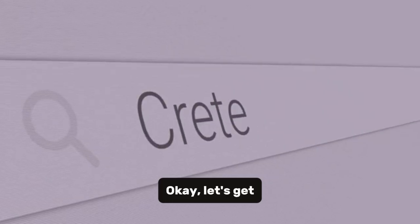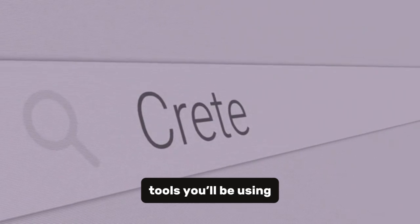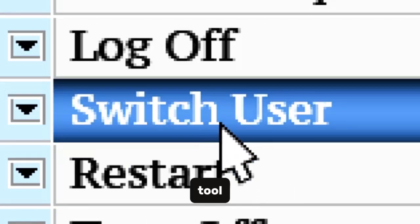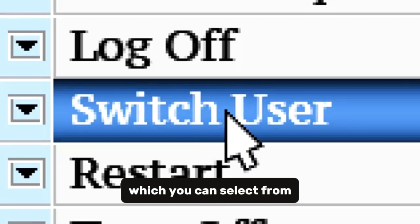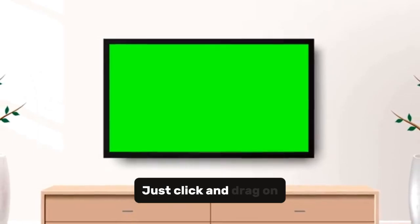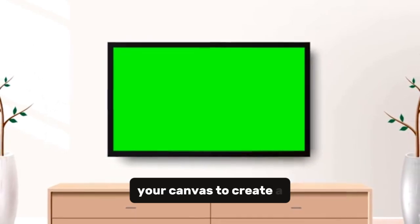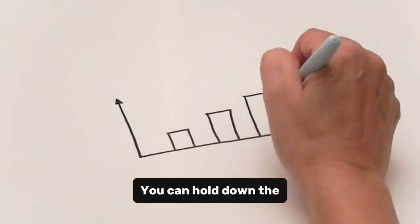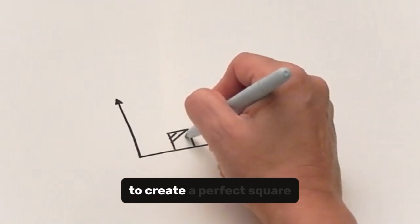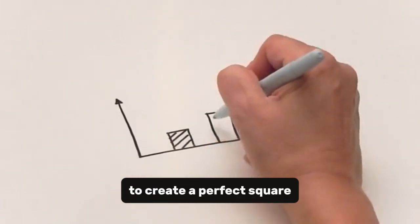Okay, let's get hands-on with some of the basic tools you'll be using all the time. First up is the rectangle tool, which you can select from the toolbar or by pressing R. Just click and drag on your canvas to create a rectangle. You can hold down the Shift key while dragging to create a perfect square.